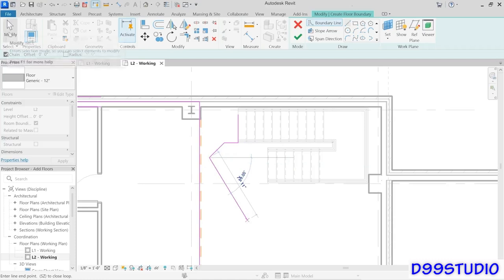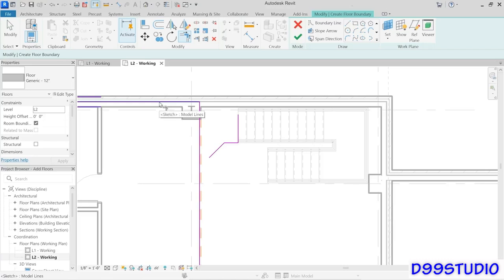I'm going to click the Modify tool to finish, go to trim and extend to corner, take this horizontal line at the top and extend it to this vertical one that I drew here, take this diagonal line and trim it down to this vertical one here. Again, remembering to pick the lower portion because that's the piece that you want to keep. So now that floor shape makes a little bit more sense and allows folks to get up the stairs properly.